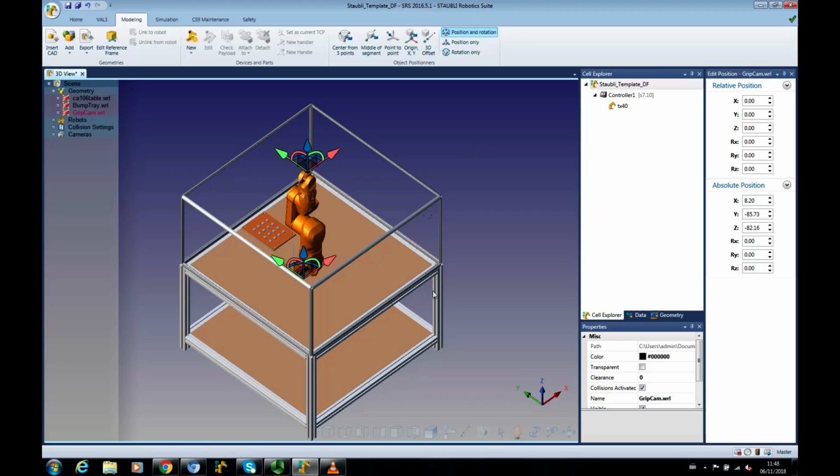Okay. Looks like, let's have a look. There you go. Hidden away there. We can see that what's happened here is it's pointing down, our robot is pointing up. So what we'll do is we'll rotate it 180 degrees. Then what will happen is that the reference frame will need rotating back. Then we're going to slowly move it somewhere close to the end of the robot and then attach it.